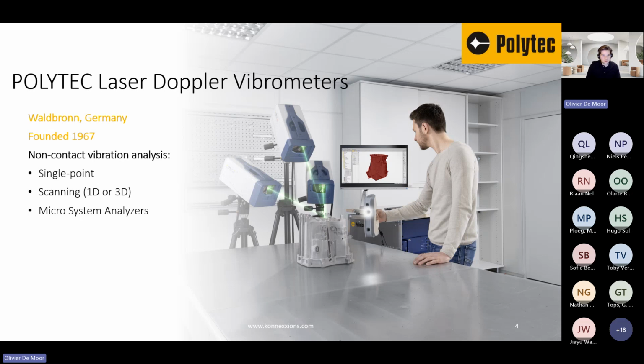With the scanning laser vibrometer, this is the same method, but now you use two steering mirrors to move the laser beam in X and Y direction over your surface, so you can visualize the deflection shapes of the vibration. With the microsystem analyzers, you actually implement a scanning laser vibrometer in a microscope to measure on very tiny objects like MEMS structures or biological tissues, and you can also visualize the deflection shapes of your vibration.